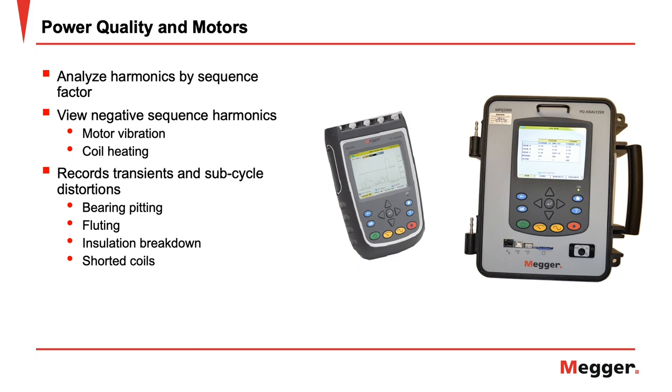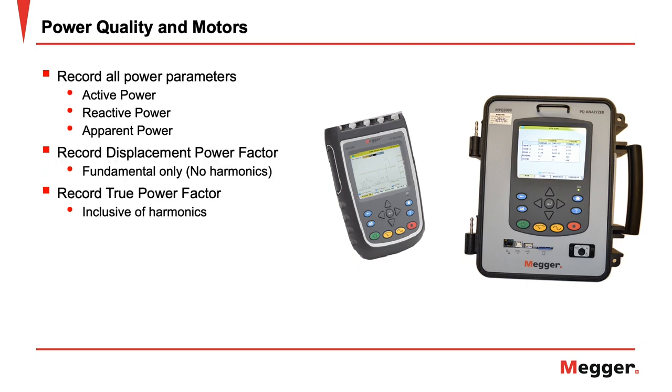It will record both transients and subcycle distortions that can cause bearing pitting and fluting, as well as insulation breakdown, which will lead to shorted coils. The analyzer will also record all power parameters as well as power factor. A low power factor can cause motors to be unable to obtain full power.